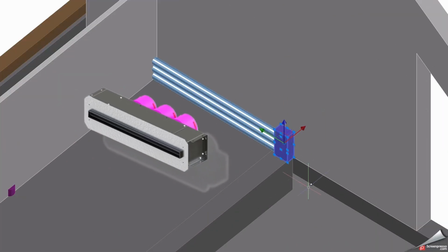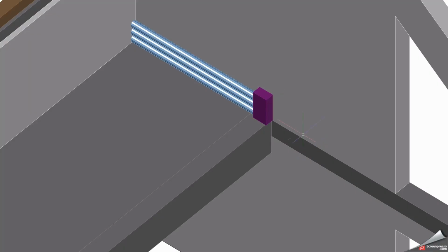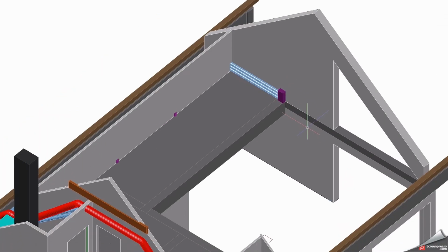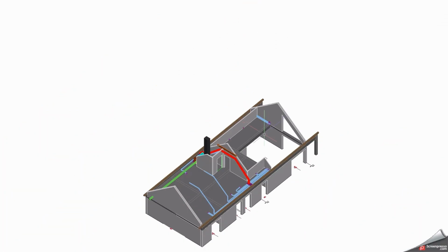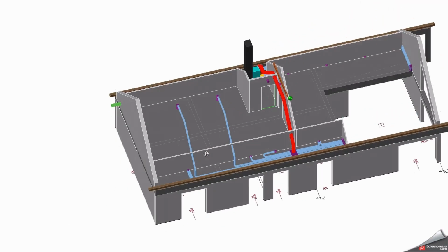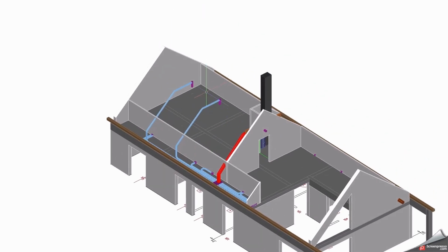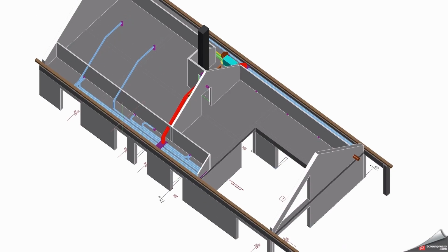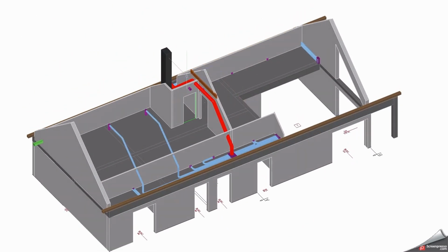I'm counting on the airflow directed at the hot chimney to help distribute the heat more effectively throughout the living room. The final point concerns the attic's ventilation. Its intended use has not yet been precisely determined. At the moment, it's just serving as a storage room. In the attic, we will install 3 air diffusers, 2 on the ceiling, routed from the western junction box, and 1 on the wall of the technical utility room.